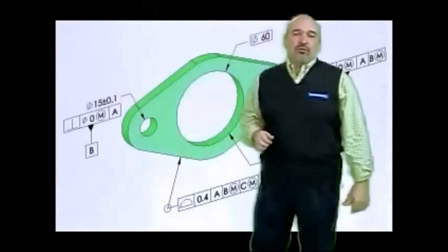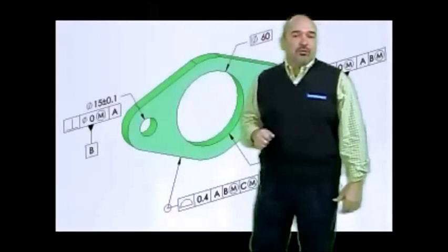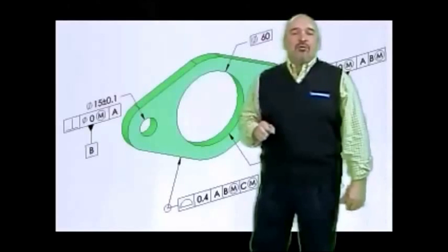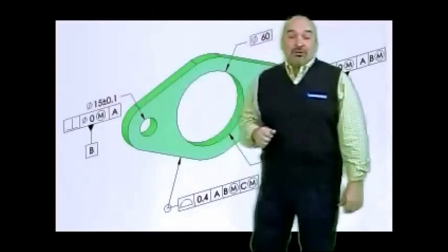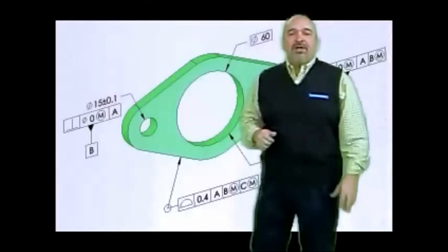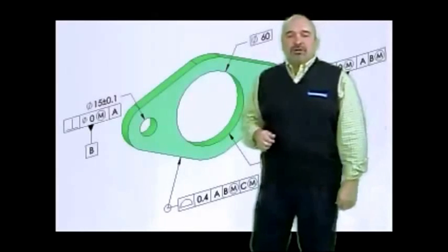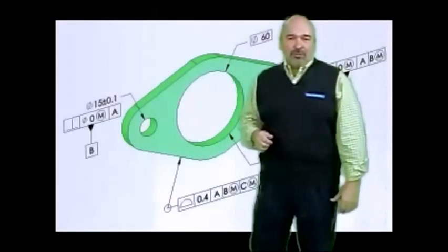This doesn't change the profile tolerance zone, which is still 0.4. It does allow the profile tolerance to float a bit when the datum features are made larger than their virtual condition. Let's say this part is to be inspected using an overlay on an optical comparator.